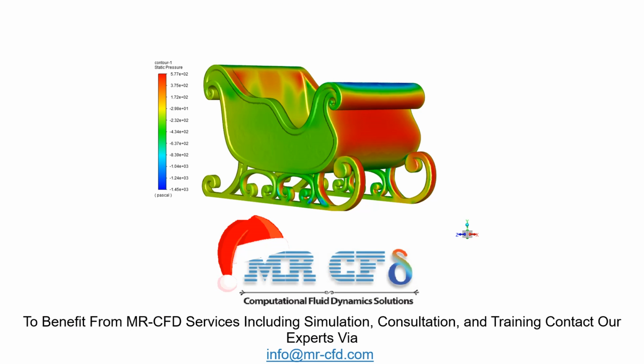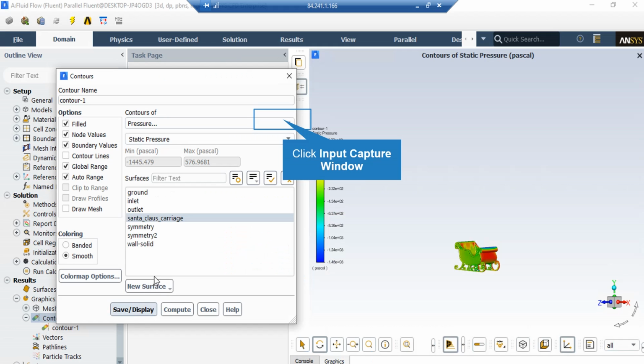Now in this slide you can easily see the pressure distribution on the carriage outer surface. Also you can see that in the front section of the carriage the pressure value has increased, which is due to the formation of a stagnation point on the front section.